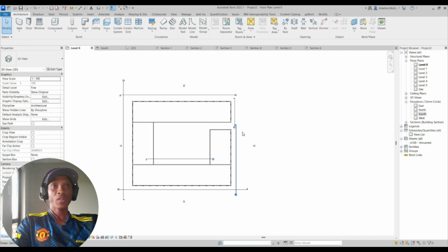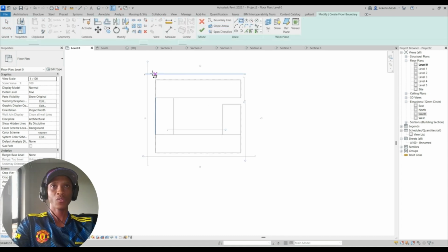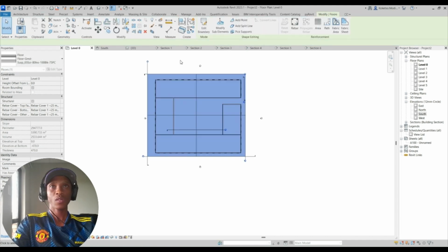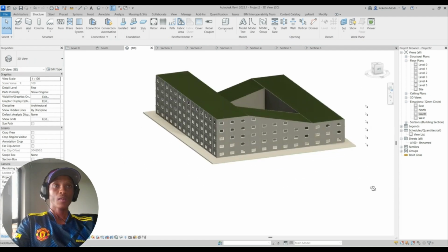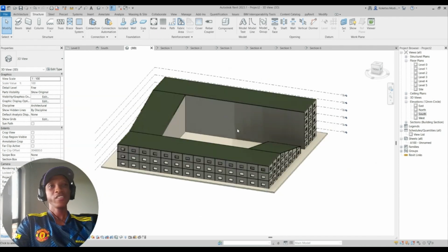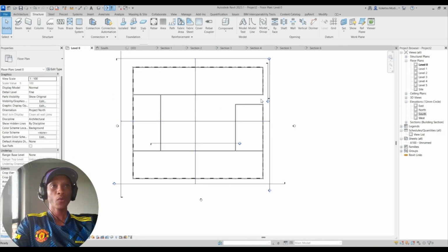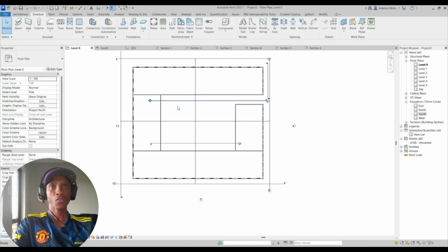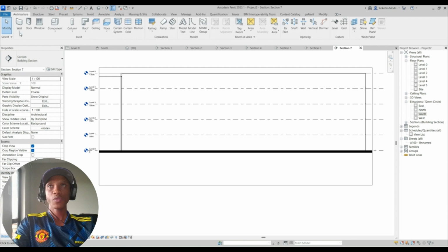So obviously, I'm just going to place a floor, just a basic generic floor right on the bottom. Place it like that, and say finish edit mode. 3D view. This is how it looks. So yeah, actually, let me just place the other ones on the interior. So I'm going to place another section, the side. Let's just reduce its view extend. Let's open it. And I'm going to place some sweeps.